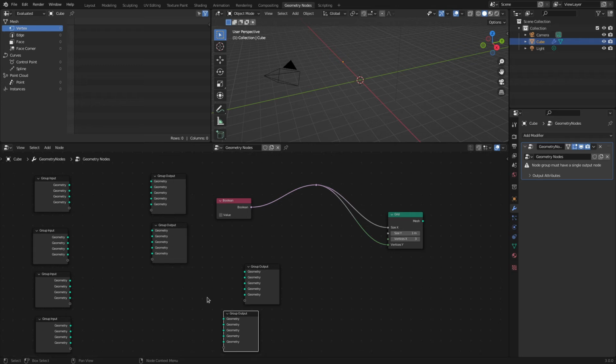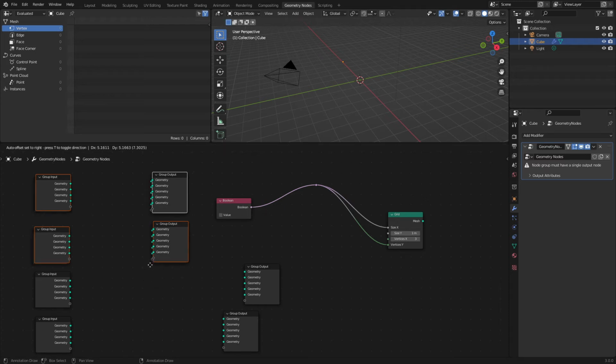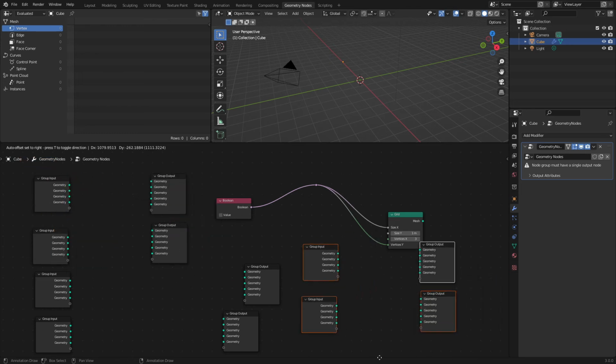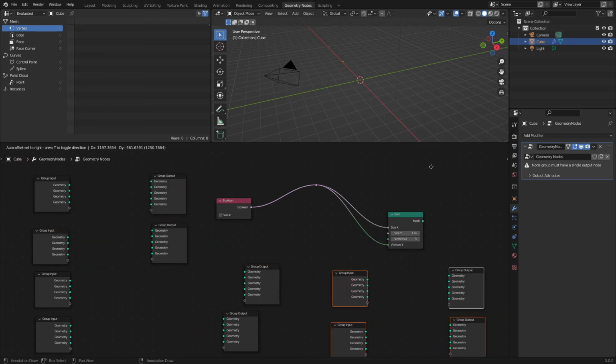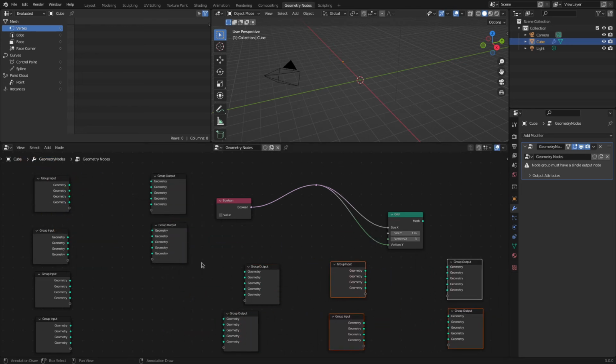All right, now as far as duplicating nodes, we've gone over this multiple times previously, but just to go over it one more time, to duplicate a node is Shift D. All I have to do is have a node selected or a group of nodes selected, and by holding Shift down and tapping D, I have duplicated them and gone into a grab. So now I have all four duplicated. I can move them wherever I like, and then just click to drop them.